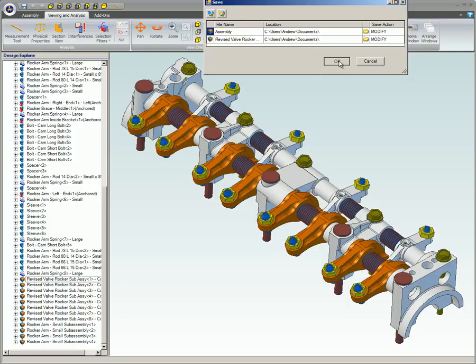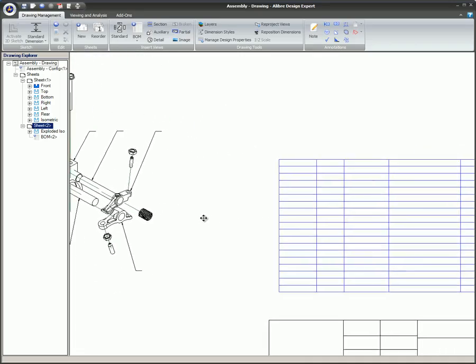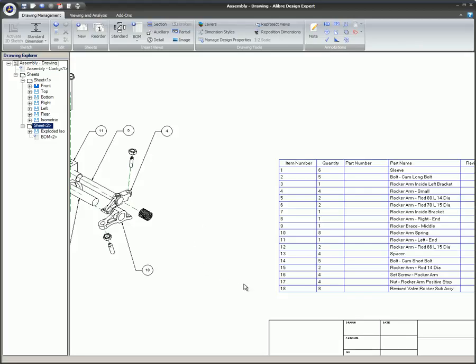If you edit the bill of material, you can change the item number so it will be different in the callouts. To do this, click on the cell you want and enter in a whole number you want to use. You can then switch to a different cell and enter in another whole number value.